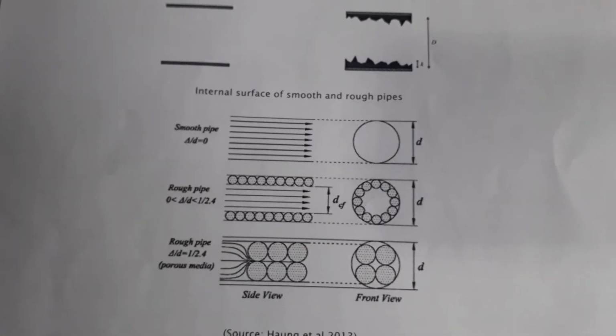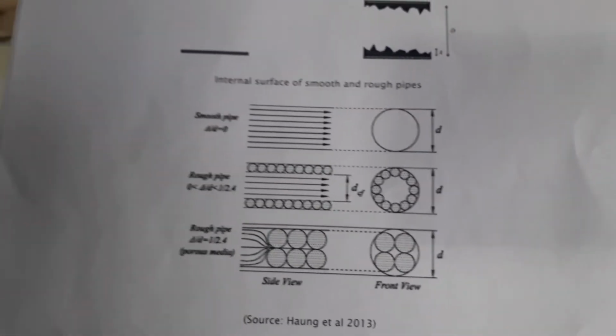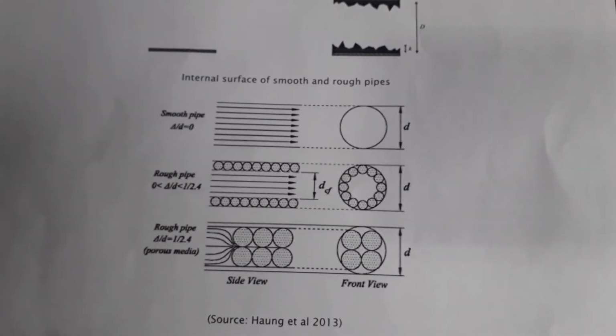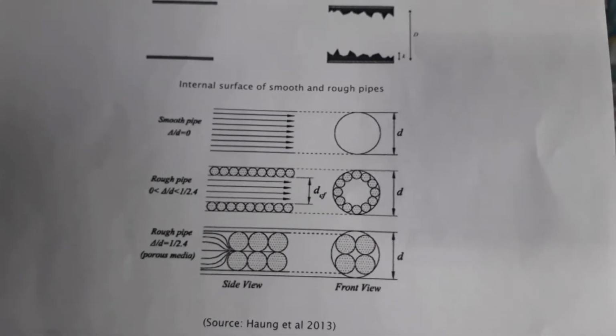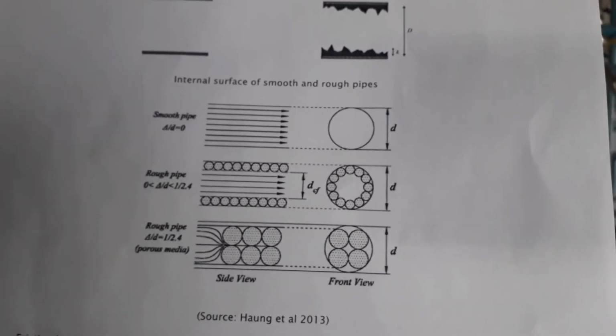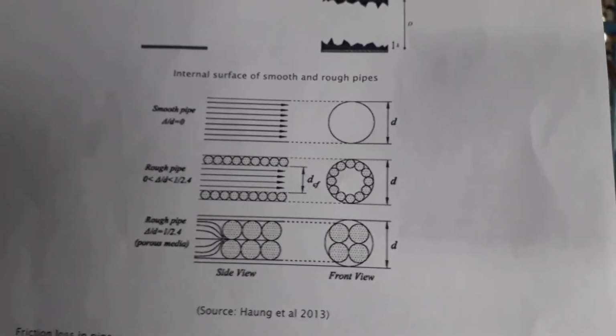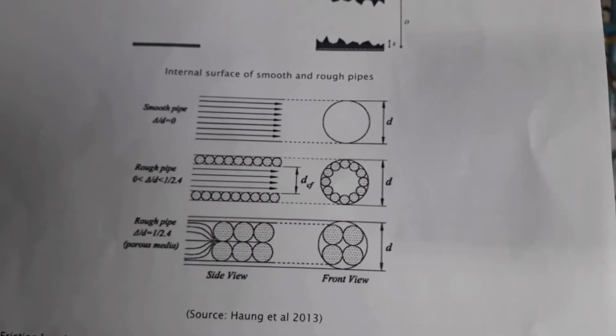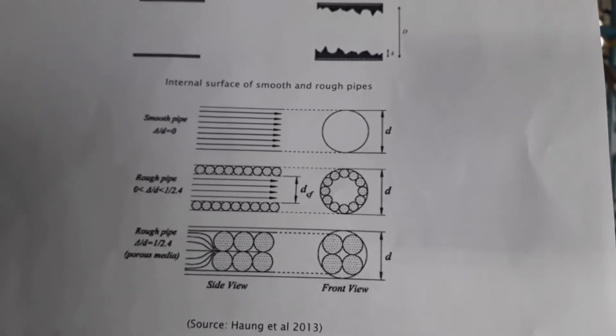Pipes with a smooth surface do not account for large friction loss, whereas pipes with less smooth walls, such as concrete, cast iron, and steel, require a large amount of energy to overcome the friction induced in the pipe due to the viscosity of the liquid. The rougher the inner wall of the pipe, the more the pressure loss due to friction.